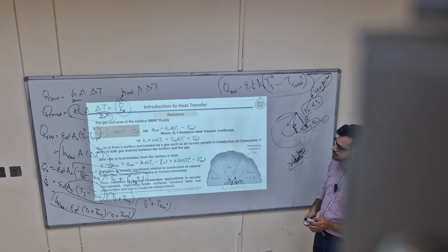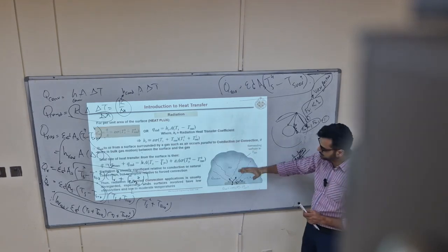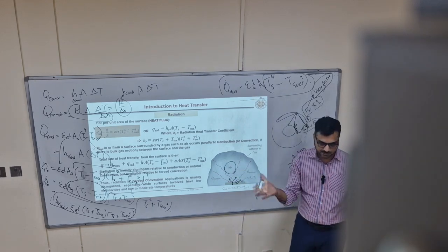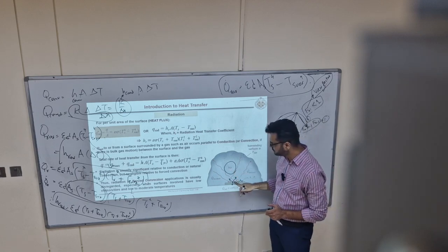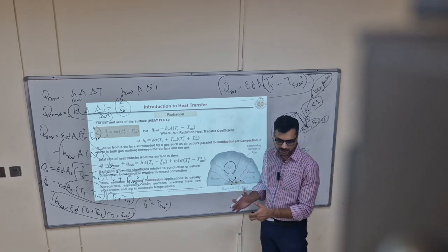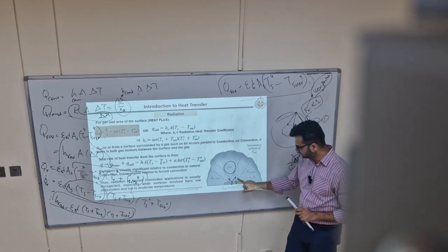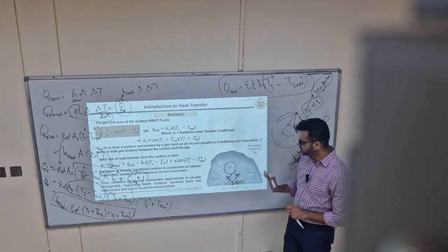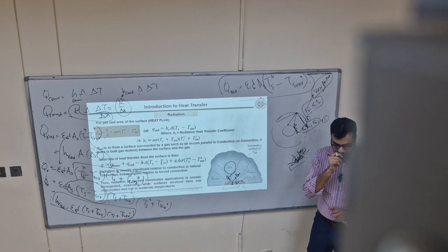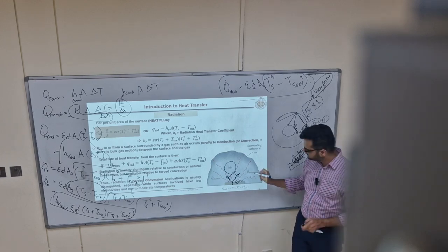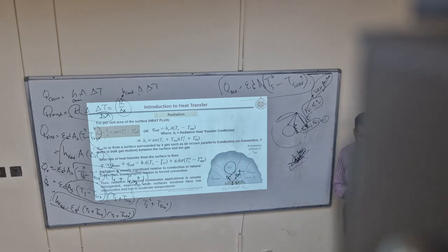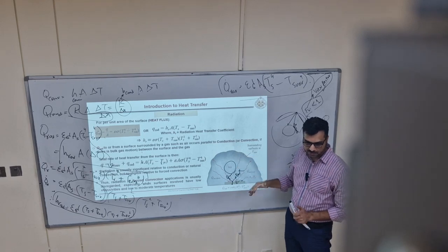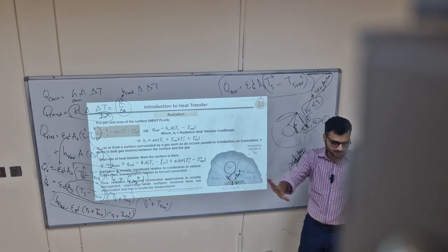That is the next topic. But before, we will solve a question. So this radiation heat transfer, if there is natural convection of air, generally, you cannot or you should not neglect the radiative part. You should calculate Q radiative plus Q convective. But if it is forced convection, and if there are liquids involved, then this is definitely negligible compared to forced convection, because the temperatures with which we are dealing are normally below around 100, 200.